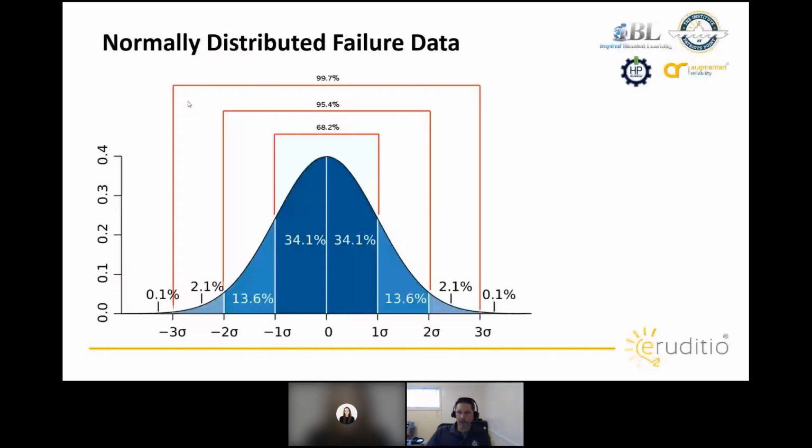All right, another question came up. Is mean time to repair the best way of measuring the effectiveness of a craft, or as a KPI for performance on a performance contract? Mean time to repair has so many different things that feed into it. So we want to understand what we are trying to do. If we're looking at how our overall logistical system and support system is, mean downtime is probably a good measure that we're going to use.